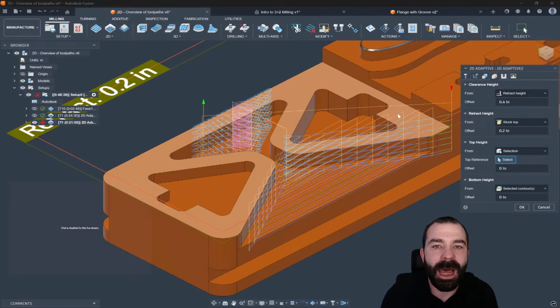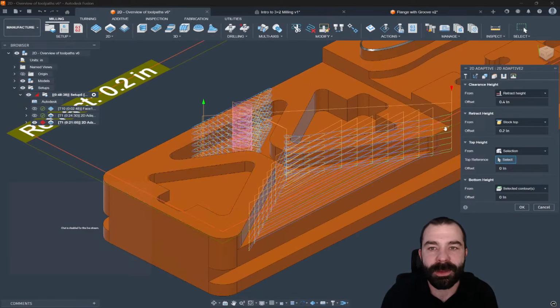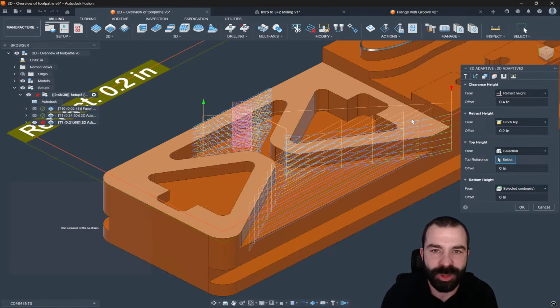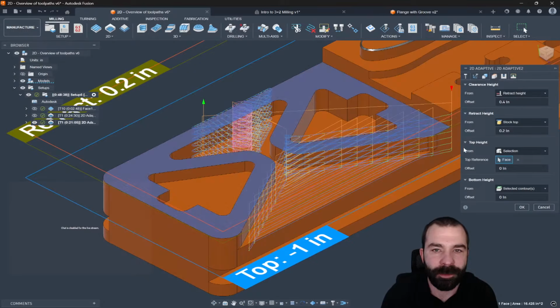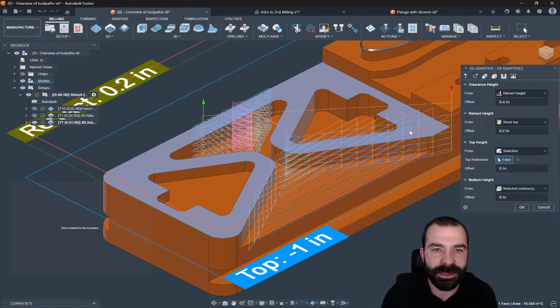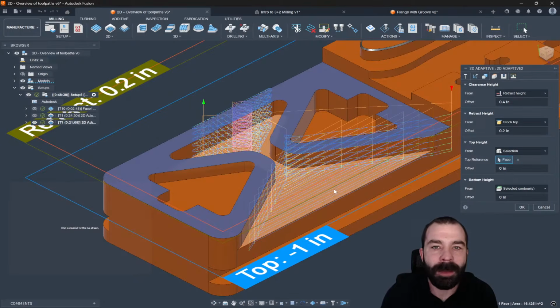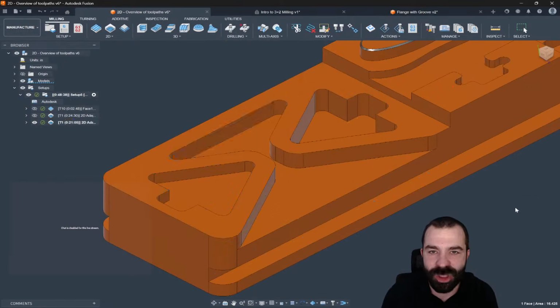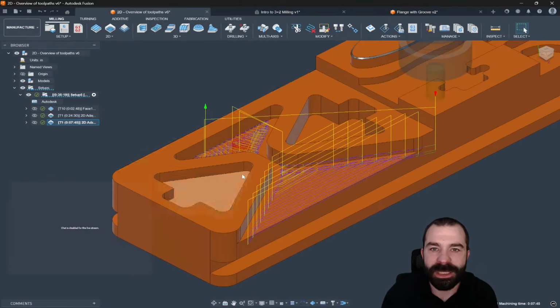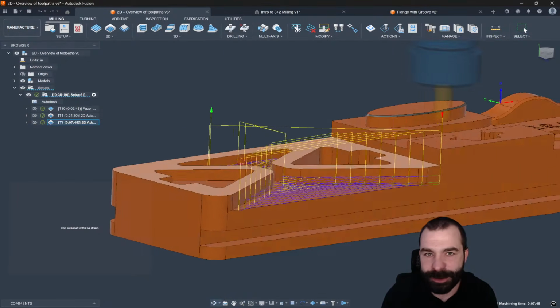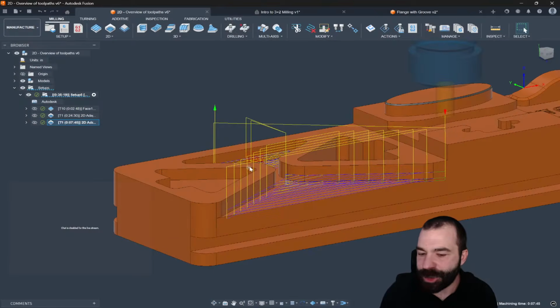So again, I can either pick a surface or I can pick a point or an edge. So I'm going to pick this floor now. So again, we're going to machine from the selected surface down to my selected floor location, which is the edges that we picked in the geometry tab. And just like that, you're now going to notice as my multiple depths have been trimmed up and we're jumping up and over as you're seeing.